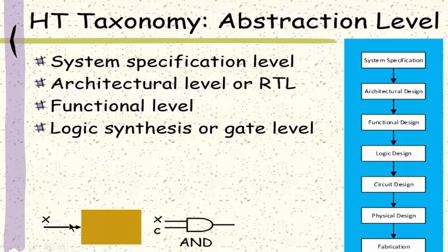For example, we can replace this control signal X by a 2-input AND gate. The attacker will set the hardware Trojan's trigger signal C to be 1, so the system will behave normally. When the attacker wants to disable this block, he can simply set the hardware Trojan trigger signal C to be 0 and disable this entire functional block. This type of hardware Trojan is sometimes called a killer switch because it can disable or kill a hardware component.